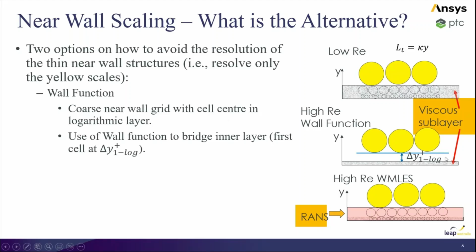If we take the log law approach, we have a certain cell size here, and we say that we've got a logarithmic profile at a certain height there. That's just like you might do in, say, a K-epsilon model, where that first cell needs great care, because if we put it too close to the wall, it's unphysical. If we put it too far away from the wall, it's unphysical. And we're not really resolving things then. We've also lost our ability to do things like separation properly if we're using a log law, because that will tend to keep the flow attached if we've got a curved boundary.